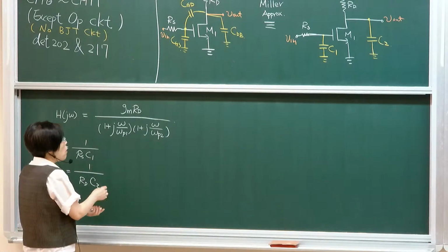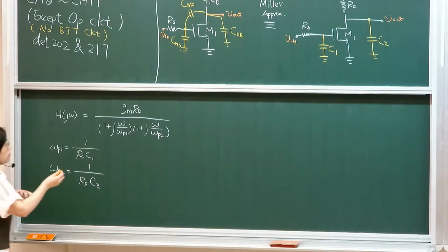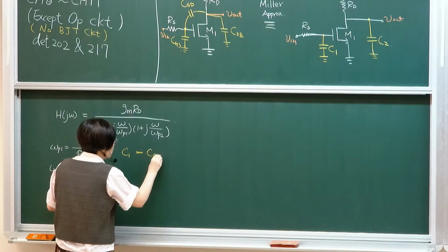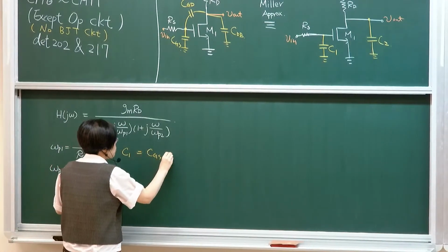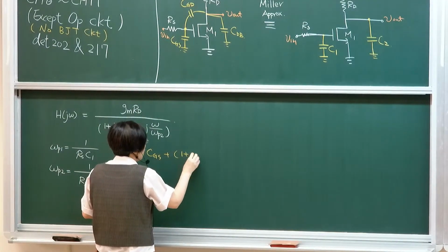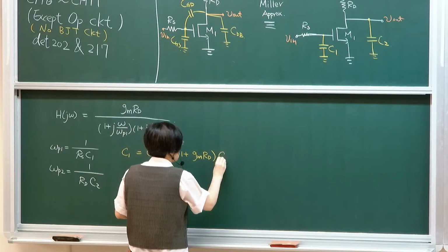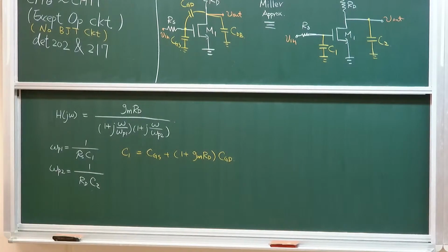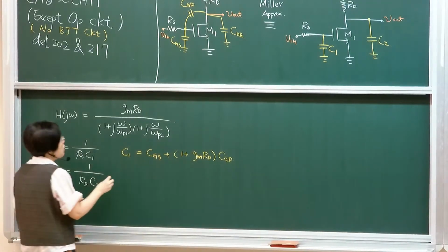So then you need to construct what C1 is actually composed of. C1 is composed of, of course, its original CGS. You have a capacitance, and then there's Miller capacitance. CGD is effectively amplified by this inverting gain. Because of the inverting gain, the opposite side is sinking. Therefore, it's very hard to pull your input node.